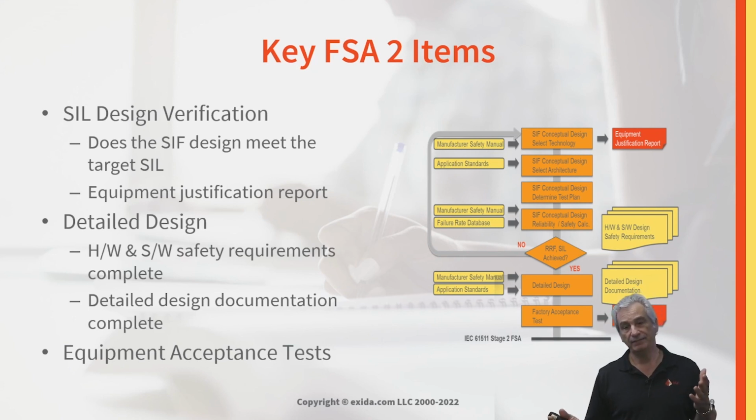where the initial validation is done for the application logic with the logic solver. And here again, within the design phase, were the SIFs designed correctly? Did the SIL verification meet target? Do we have evidence of equipment selection? In other words, the equipment justification report that's required.